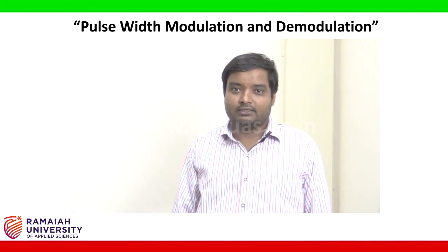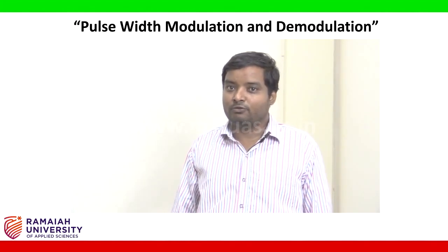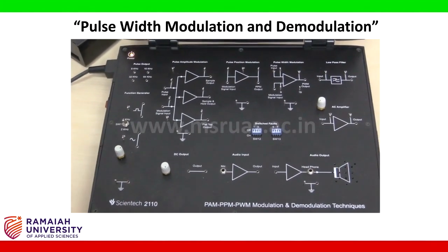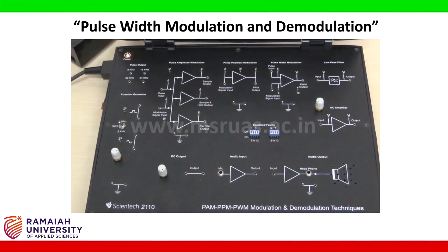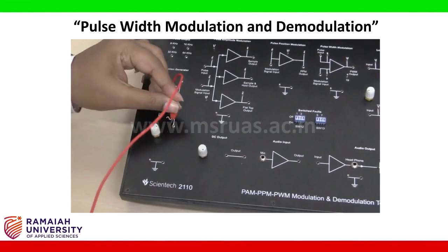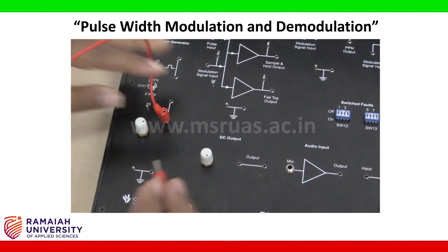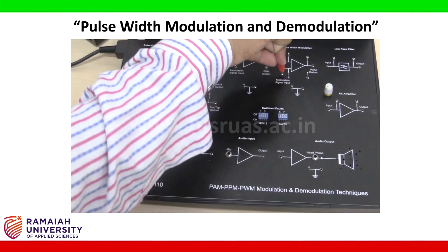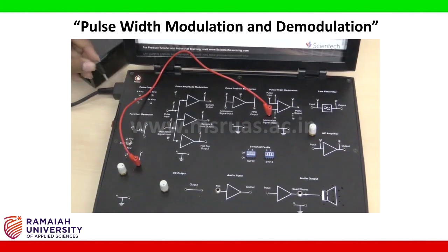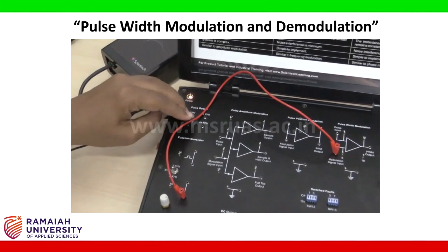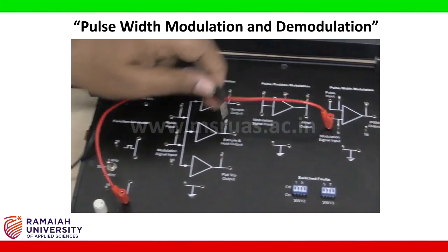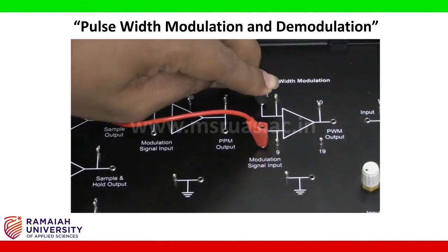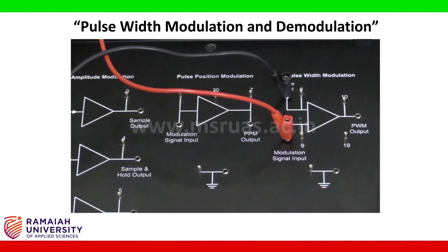Let us start the connections for the Syntec 2110 board for the pulse width modulation experiment. Sine wave, which is the modulating message signal, is connected to the modulation signal input. Pulse output of 32 kilohertz is connected to the pulse input of pulse width modulation block.